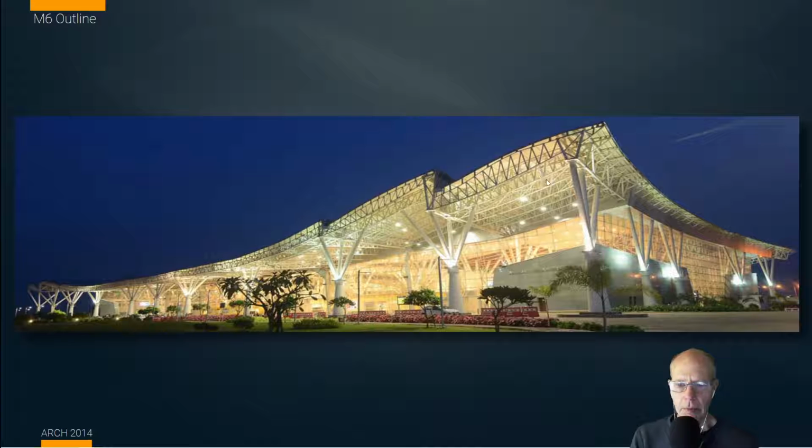So here we have what I think are really attractive columns supporting the loads of the building. And if you look in, you can see these repeating adaptive columns here, but you can also see how that's carried in to what looks like an expo hall here. Another thing to call your attention to is the fact that this truss isn't all one thickness up here. So in the center, where there's the most amount of load that wants to bend this roof system down, the truss system is the thickest. And where there's less load to bend it, it thins down.